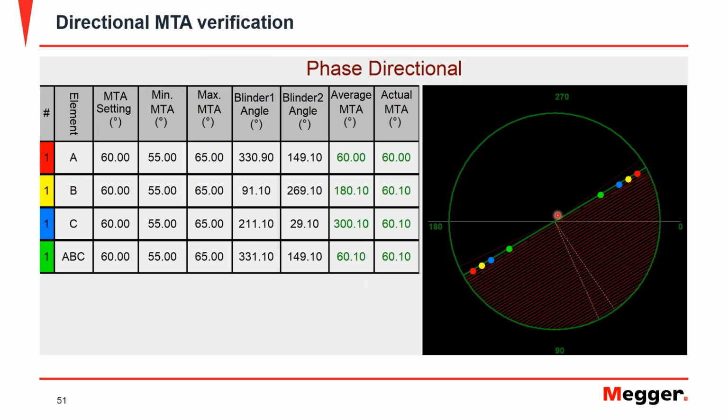This one is a little bit, I'm going to say, more challenging to pass, because this one is going to keep the operating signal at a value higher than your pickup, and it's going to move your angles from no operation and into operation.